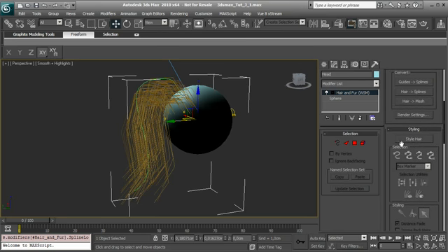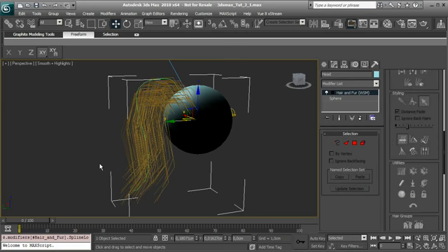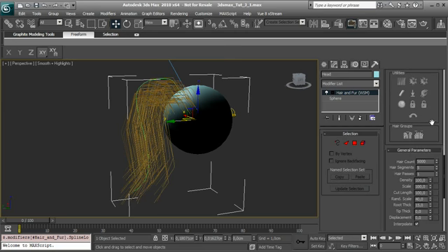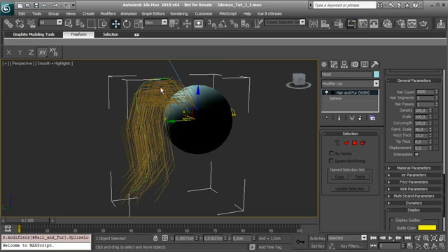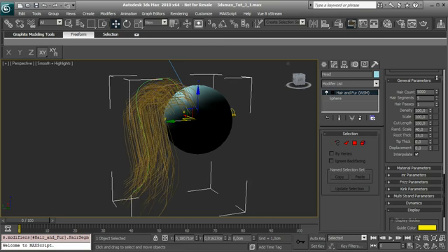We have the possibility to style the hair, but we are using the spline guide, so it's more simple. But you see that our hair will have too low a value for the segments, so we have to change the hair segments to have curvy hair, and we can use, for example, 30.